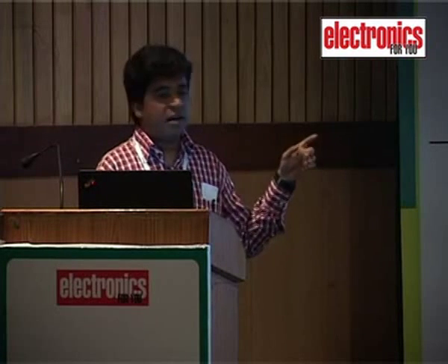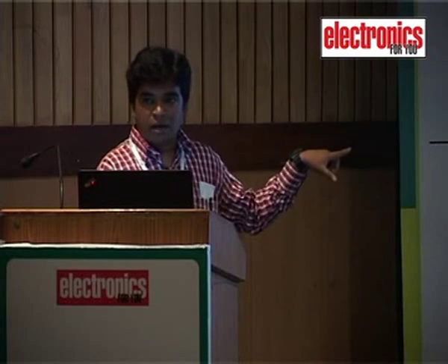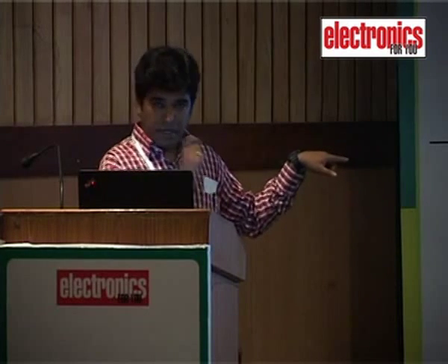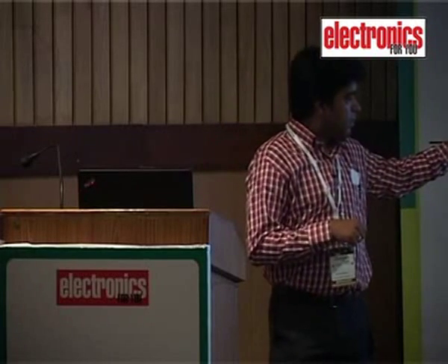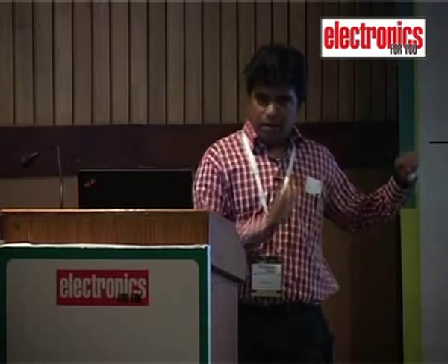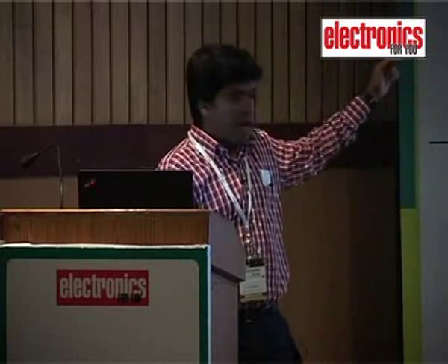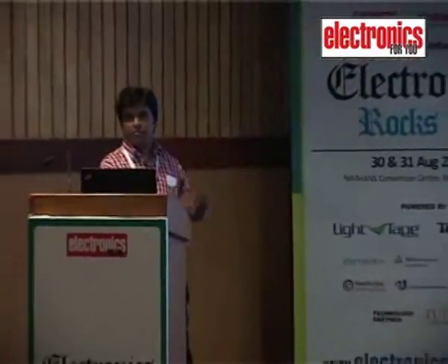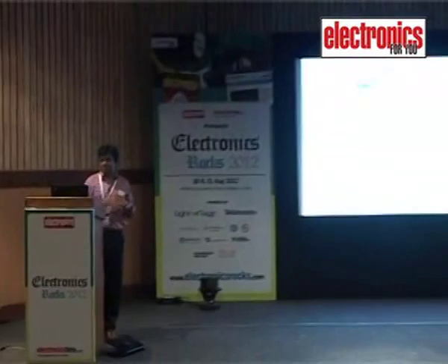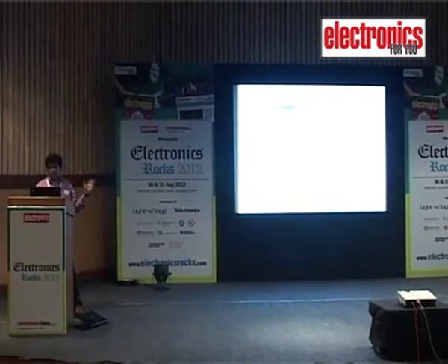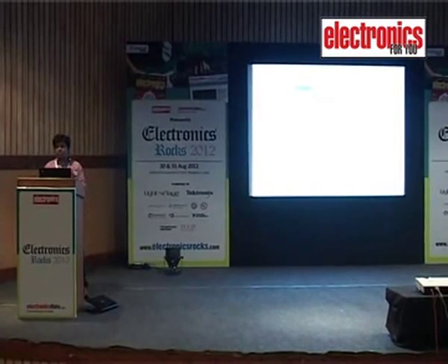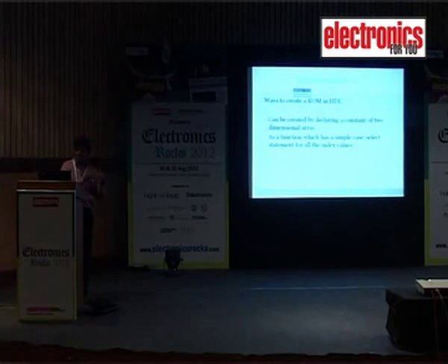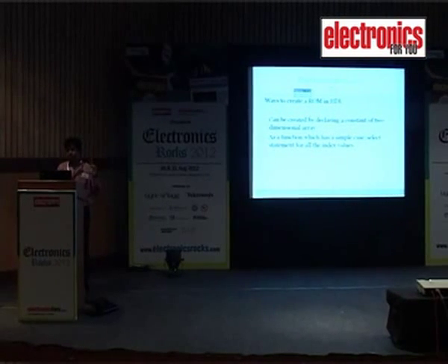The only reason here is that if I have to decode anything at runtime in my simulation, for a particular address, what kind of data is being accessed at the output, I have to refer to this line where D is assigned to ROM at that particular address, and then again refer to the array. This is something I'm not very fond of. So in the second case, since we have a simple case select of index values, we will simply use that value, and we will come to know the address and what the data will be. I'll show that in actual code.